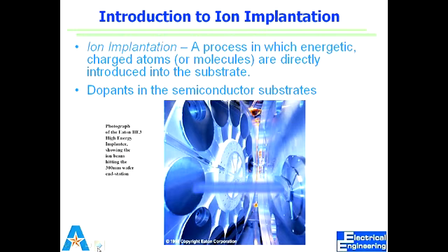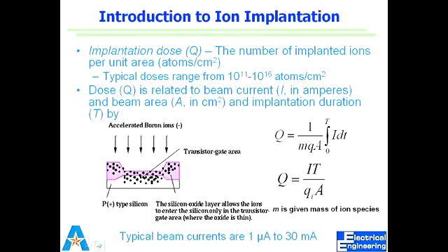So this is just an example showing a wafer and an ion beam which is being bombarded on that level. So these are all wafers which are probably coming in front of the beam in turn and getting bombarded. There's an actual picture, not a conceptual one. I guess it's an actual, because it says Eaton HE3 high energy implanter showing the ion beam hitting this wafer end station. So I think this is the real thing. So the beam is very tightly focused.